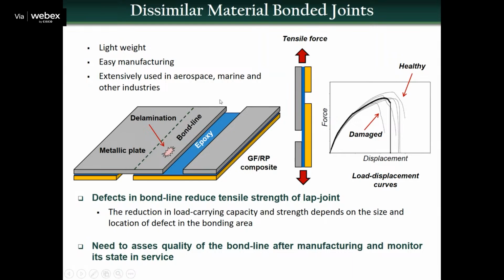So if you go to inspect the aircraft, or before you just enter the aircraft cabin, you can look at the aircraft fuselage, the skin. There you'll see a lot of rivet holes there. That's how they joined those different layer structures together, and to form the lap joint